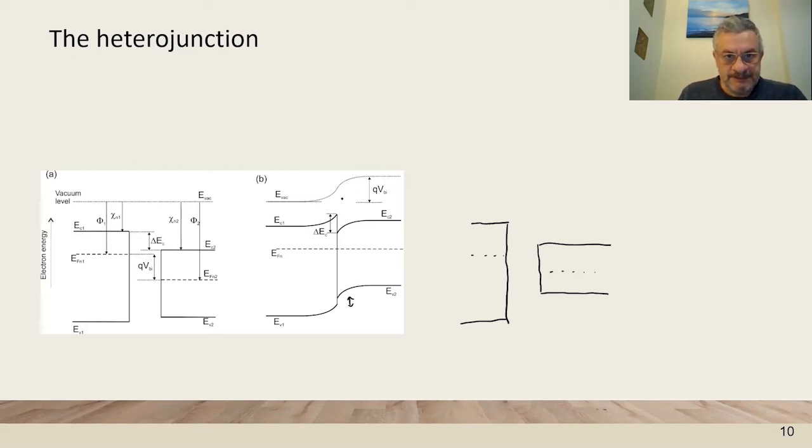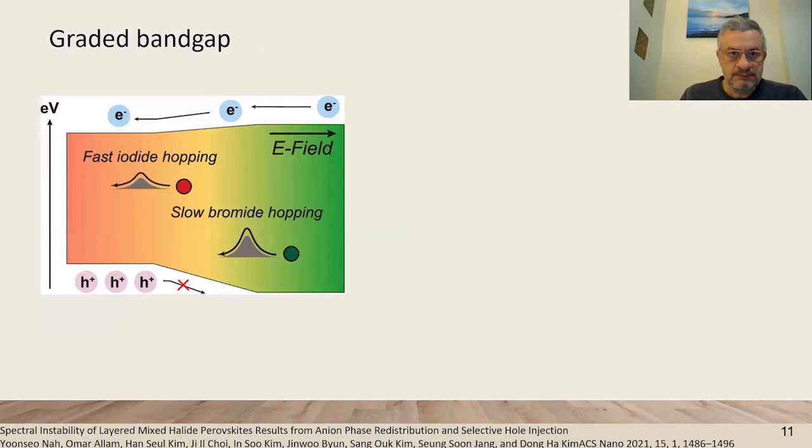So that this is the very useful feature of the vacuum level and can show us the evolution of the electrical potential, even when we use materials that have different electron affinities. And using a continuum of materials with variation of electron affinity, we can build intrinsic electrical fields into the material. And this is called a graded bandgap.